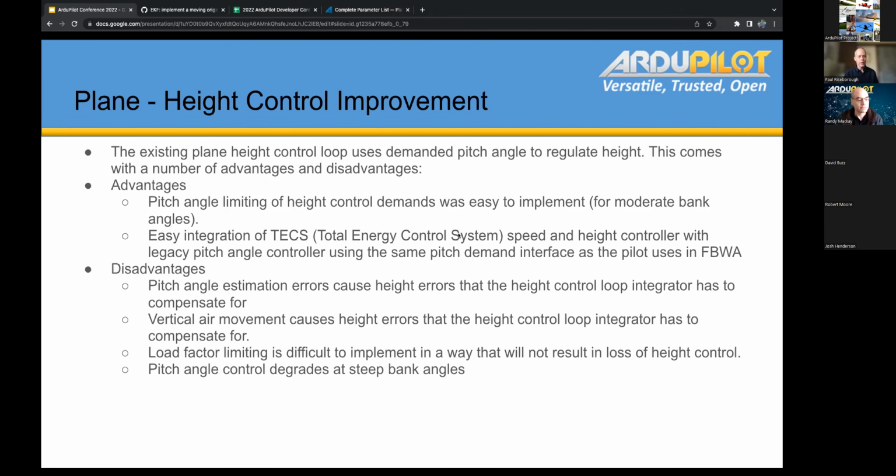Okay, all right. So by the dead reckoning, I presented this at the last conference. We have the ability, by putting in a momentum drag parameter, to capture the momentum drag of the rotors, and then you've got the ballistic coefficients to capture the mass to frontal area. I know that's fairly approximate, and not all copters have bluff bodies, but we put those in, and with a bit of tuning on replay, it's possible to get a reasonable wind estimate. At stronger winds it gets more accurate as the wind increases in strength.